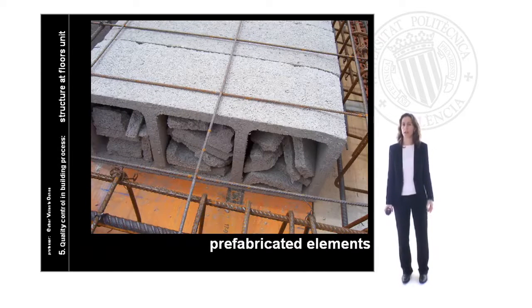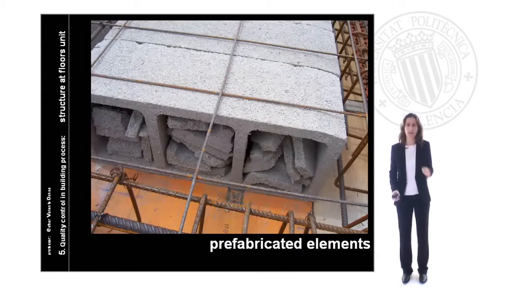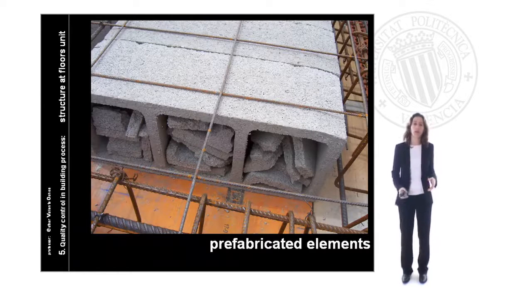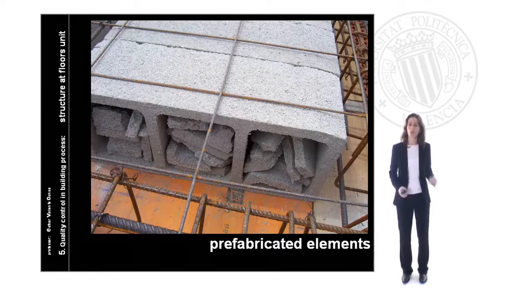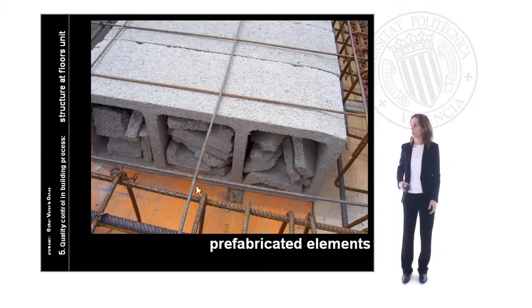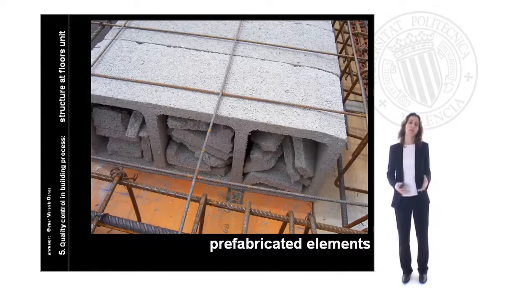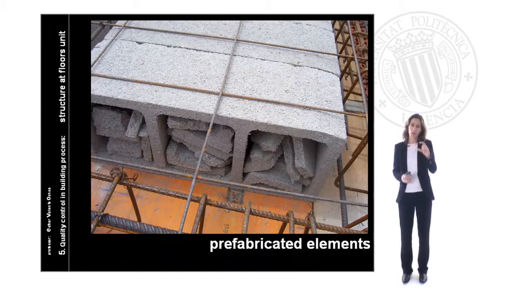Prefabricated elements have to be closed on one face, but not made by hand. They have to be completely closed by the factory, and we have to control this in order to be sure the concrete during the process of the floor in the beams will not go inside these elements, whose function is just to alleviate, to reduce the weight of the floor.